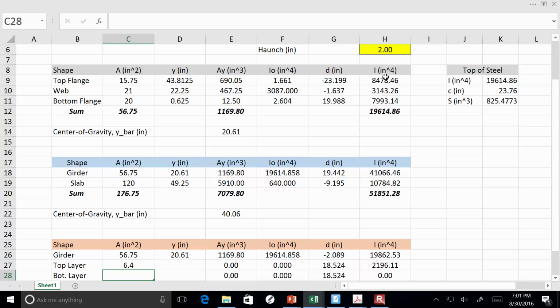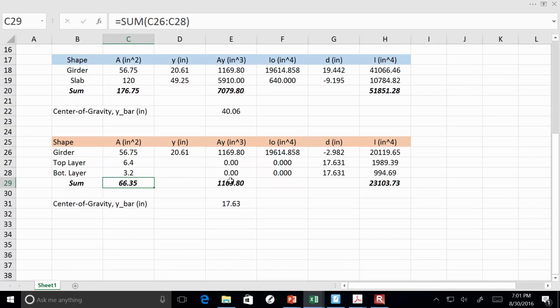For the bottom, I'm going to do something similar. I'm just going to copy and paste the whole thing. But I'm going to say 1/3. Make sense? So I've got this big lump of rebar on the top, big lump of rebar on the bottom, 2/3 on top, 1/3 on the bottom. Sound good? And that's it. The only thing left to figure out are these centroids. And I'm going to keep it pretty simple.